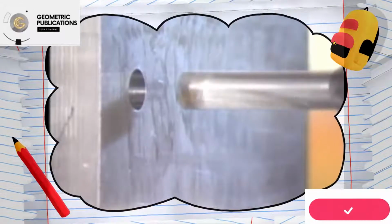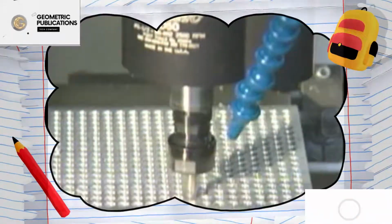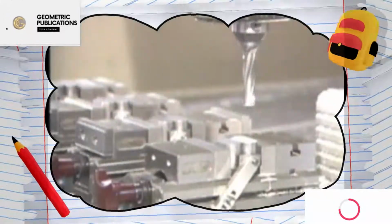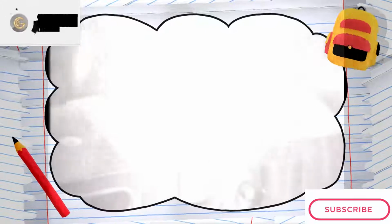Hole making is often performed using canned cycles. Once the instructions for the first hole are programmed, any remaining holes can be machined using the same instructions simply by listing their coordinates. All types of hole making and secondary operations can be performed using canned cycles, including drilling,